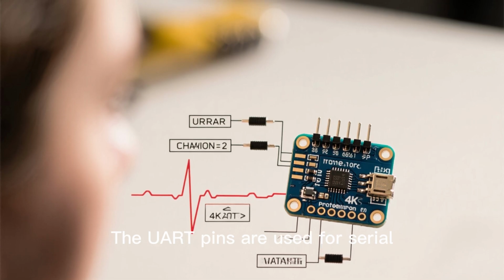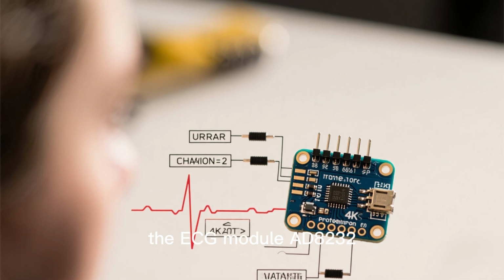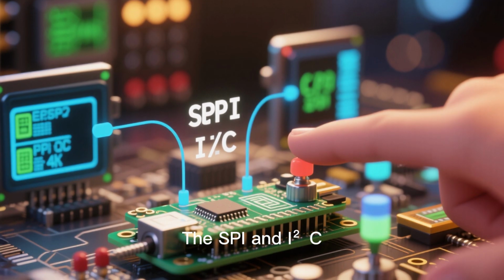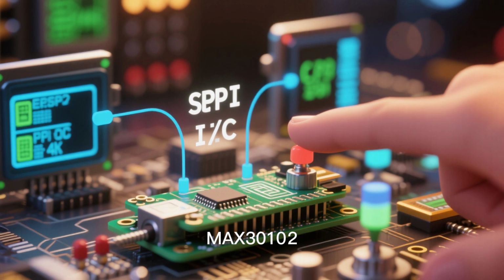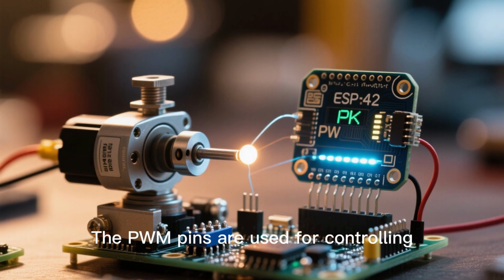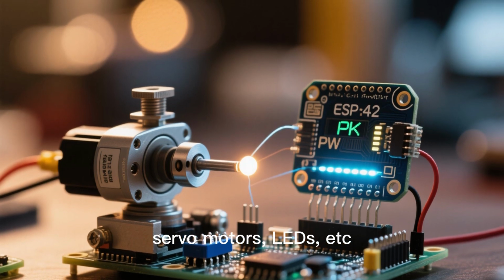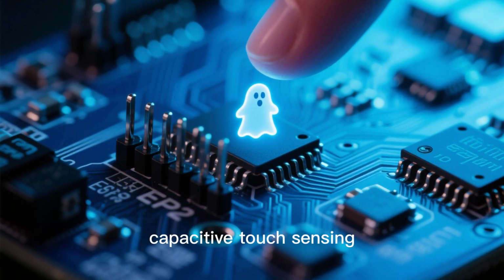The UART pins are used for serial communication like with the ECG module, AD8232, and other sensors. The SPI and I2C pins are used for interfacing sensors like the MAX30102, OLED displays, and so on. The PWM pins are used for controlling servo motors, LEDs, etc. And finally, we have the touch pins, which are used for capacitive touch sensing.